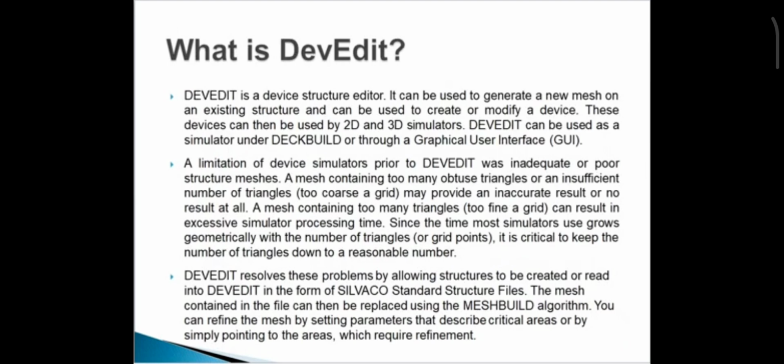To draw the 3D structure of FinFET, you must write FinFET code in DevEdit. DevEdit is a device structure editor. It can be used to generate a new mesh on an existing structure and can be used to create or modify a device. These devices can be used by 2D and 3D simulators. DevEdit can be used as a simulator under DeckBuild or through a graphical user interface.